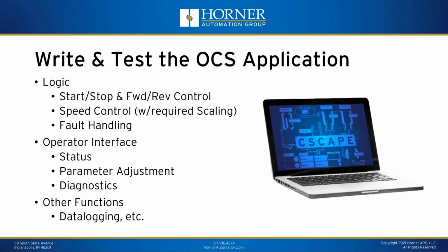Now, once you've set up your communication, now you need to get your application going. You're probably going to need logic for starting and stopping things, whether it's with just I/O control or from the network. You're going to need to obviously know what's my algorithm for adjusting speed, what happens when the drive faults out, where's that data going to come in on a communication standpoint, what do I want to have happen in that scenario, and then on the operator interface side of the application, where am I going to monitor status of communications? Hopefully that's something I only have to look at every once in a while, of course, because communications should just be working most of the time.